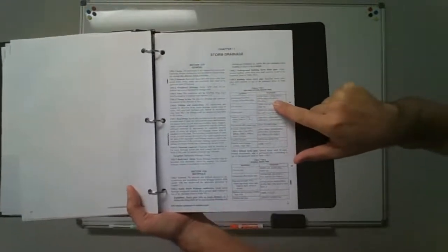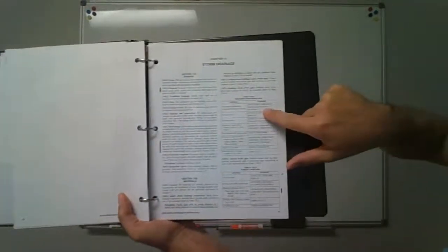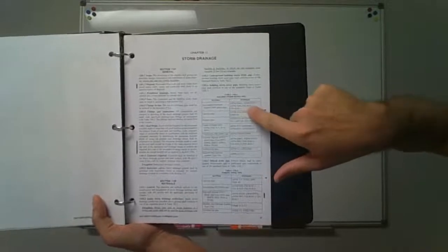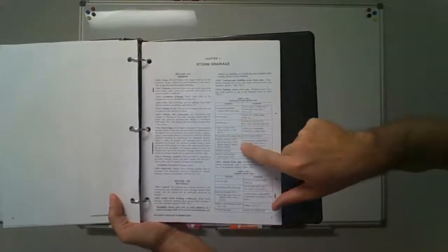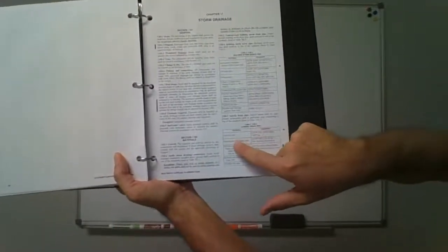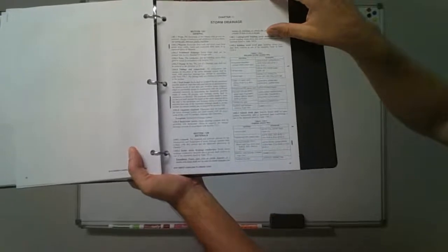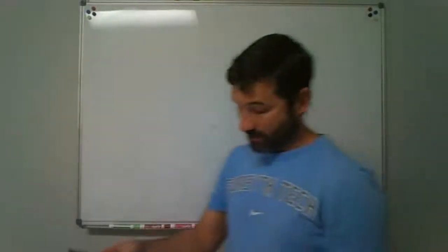So on the side of that pipe, you ought to see these numbers, or what are these numbers stamped on the side of it? Cast iron pipe, concrete pipe, copper alloy tubing. Jump down here, subsoil drain pipes. You got cast iron, PE, a polyethylene, PVC, polyvinyl chloride, vitrified clay pipe, or some terracotta there. Some of those you'll have to find. If you want to use it for that application, it needs to be found in your code book.